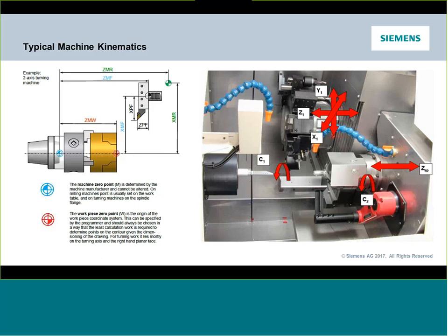Now, it's really important to start to understand where all the datum referencing comes from when I'm dealing with this type of machine technology. So machine 0 is built off of the face of the primary or the main spindle. Now, it's very possible that your machine has to go reference itself. Maybe it has incremental encoders, or the builder just forces it to go to a predetermined reference position.